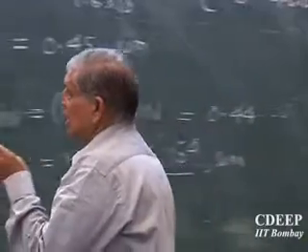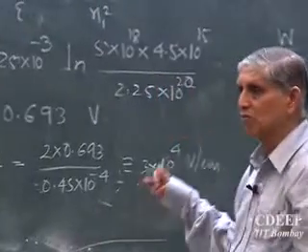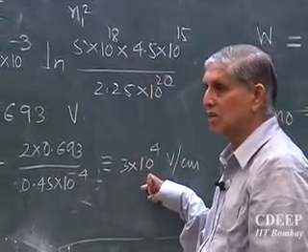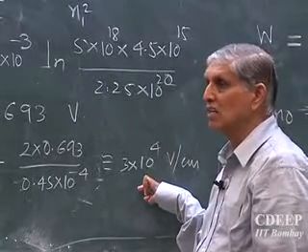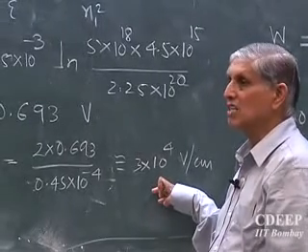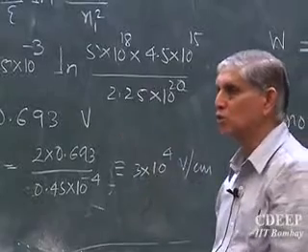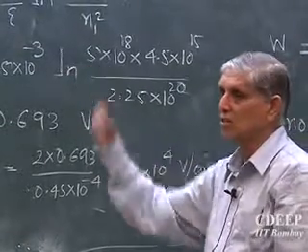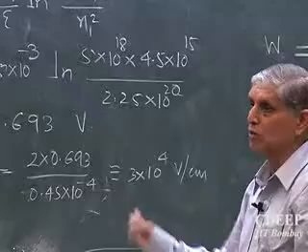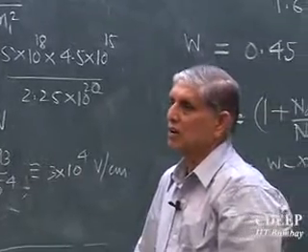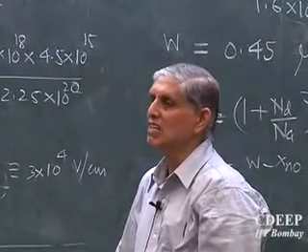So the electric field is comparatively large, 10 to the power 4 volt per centimeter, say kilovolts per centimeter. Even if you are applying no bias right now, even at the built-in voltage, the electric field is large enough. Is that point clear? This is why there is no carrier actually moving, because this electric field will stop diffusion as soon as the ions are exposed. And that is why in equilibrium we don't see any current.